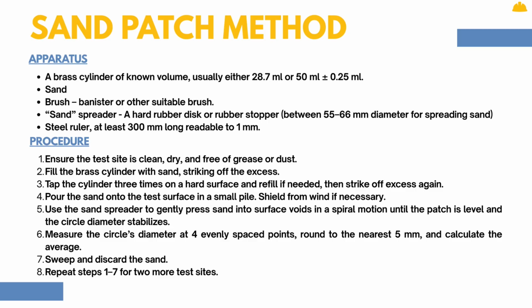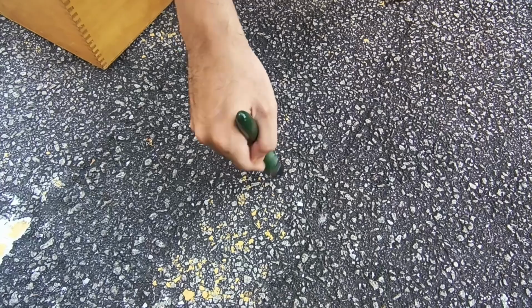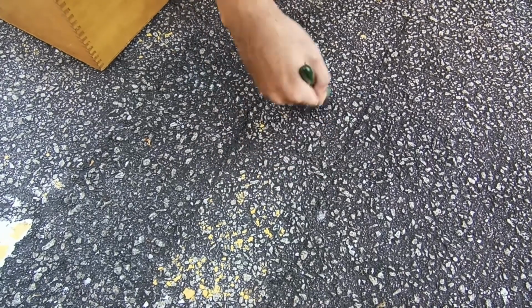Once done, sweep away and discard the used sand. Repeat the entire process at 2 more test locations for accuracy. This is us carrying out the test.